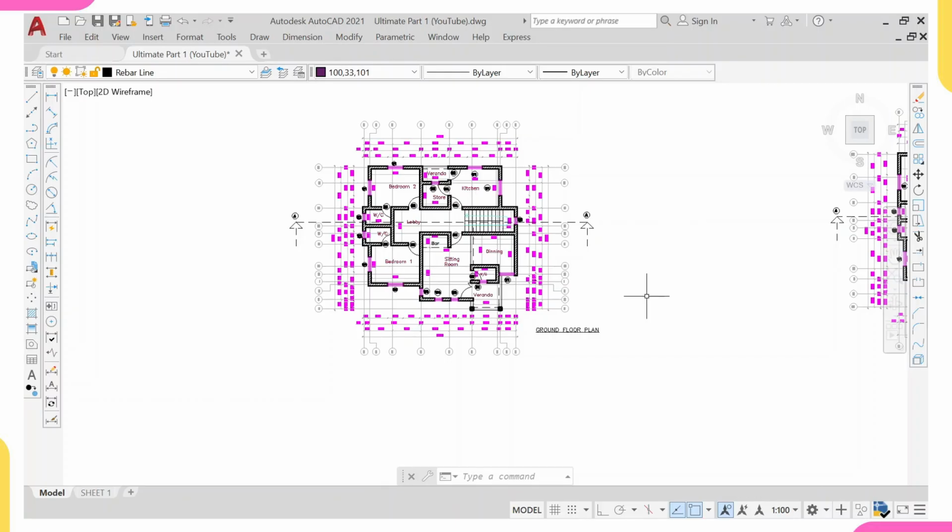So we'll study the architectural plan. Is it a residential building or is it a commercial building? Even if it's a residential building, you still study your architectural plan, because in a residential building where we'll be having a gym area at story 1, you know that the loading of that gym area slab will not be the same as other slabs. So these are the reasons why we study our architectural plan.